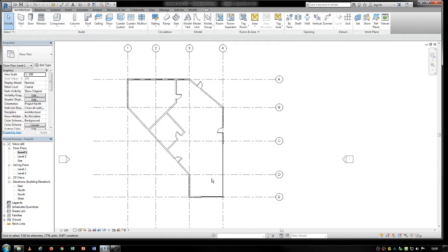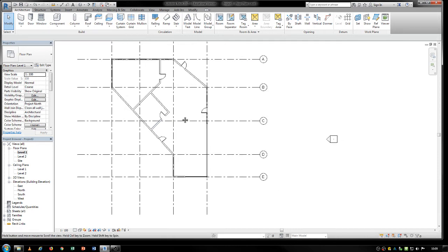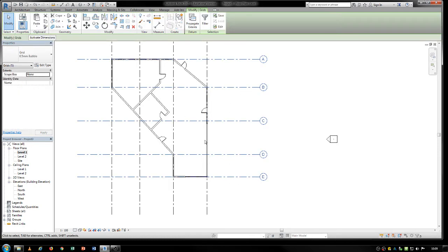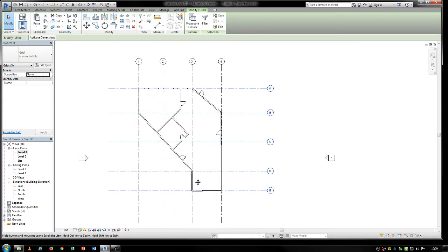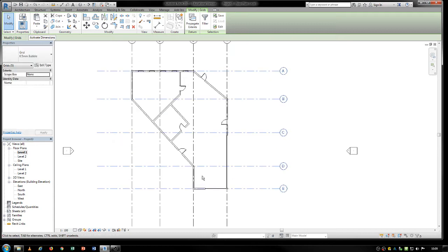If you have something at a certain angle, let's say there is a 30-degree angle between two wings on a building, and those are very important pieces. A lot of walls and columns are going to be called on an angle. So it's good to have some of these guys on that angle. So let's say these two walls that are going in this direction could define a wing over here, and I could rotate all my grids to that angle, like some of the examples that Branko showed in class. So you can have all different types of grids. Don't make it too crazy, but make it crazy enough that you can address all the elements in the building. So if there's anything specific I want to call out, I have a way to address that using the grid.